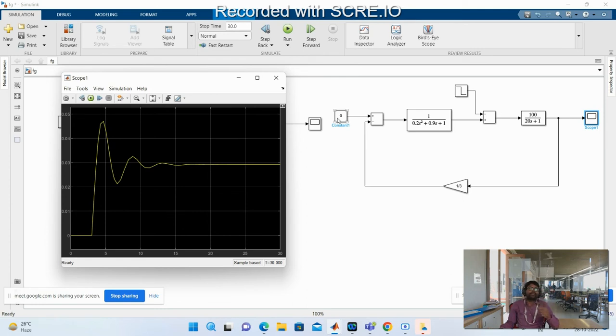But as an operator, from this control system block, your main goal is to operate your system at the normal frequency, 50 Hz. If you are able to maintain the frequency at 50 Hz, what is the delta F? Under steady state, even though the load suddenly increases and frequency comes down, you have to open the steam valve by giving a signal by changing the speed changer position.